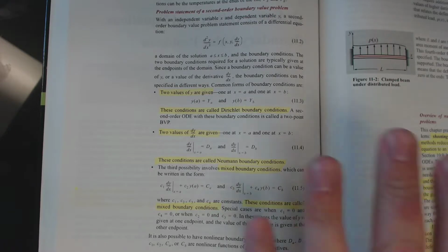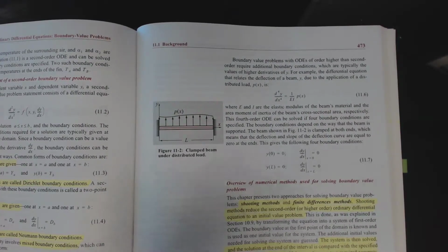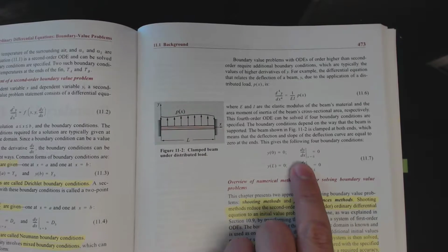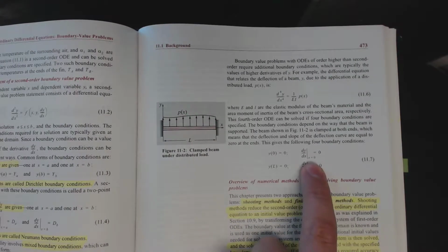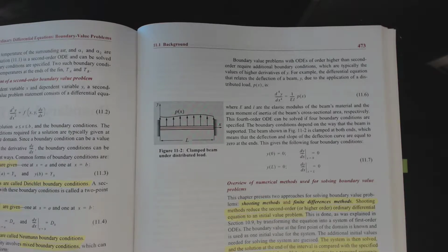Like in this example, structural beam bending, going straight through the textbook. There is the governing differential equation for the setup, and the boundary conditions are given to you quite explicitly. Since they are anchored at both ends, the slope at both ends is known to be 0, both at x equals 0 and x equals L. Since it's anchored at both ends, we also know that the position at both ends, until something breaks, which isn't modeled by mathematics, is given as 0. So that would be fairly straightforward. You would just be solving the curvature and deformation of the beam throughout the middle point.